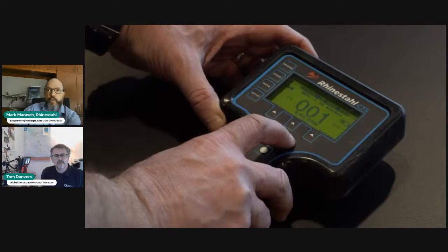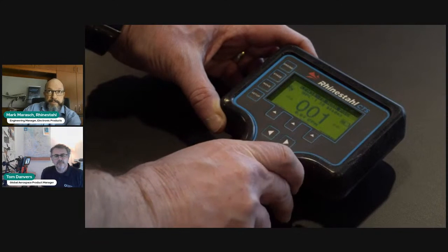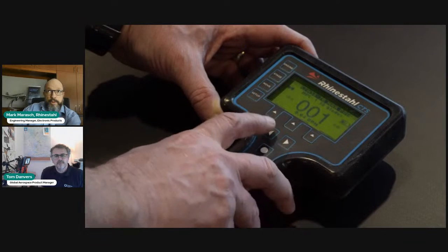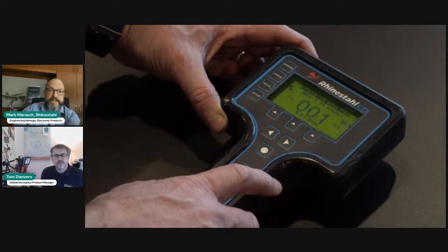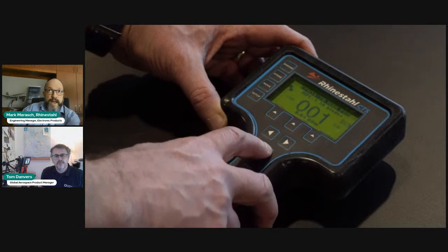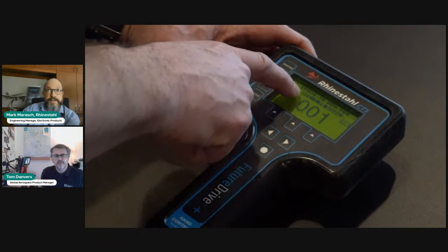We rotate the system in one direction until we see blade movement, and we've taken up the slack. Then we move in the opposite direction, and as soon as we see blade movement, we release the key again. After that, we press the circular button and we basically record the backlash we've just taken.